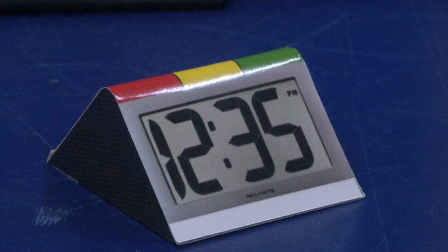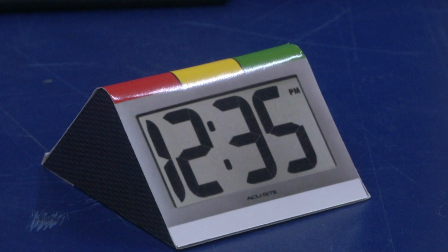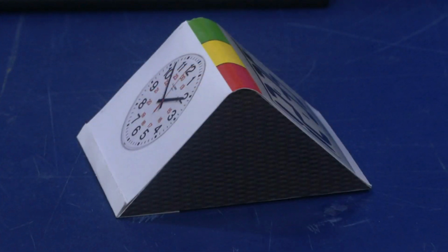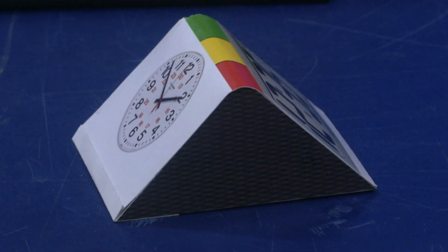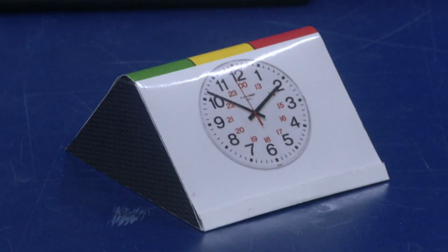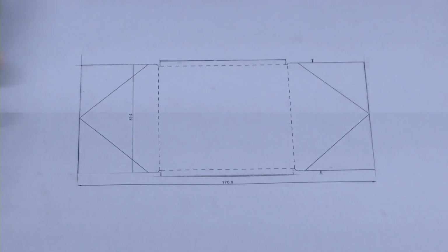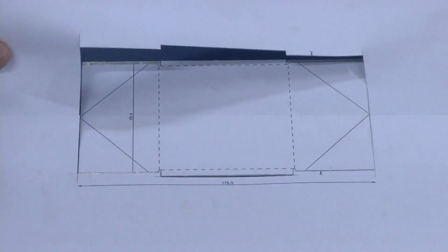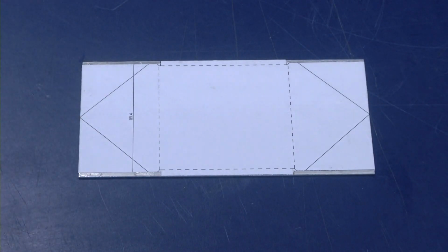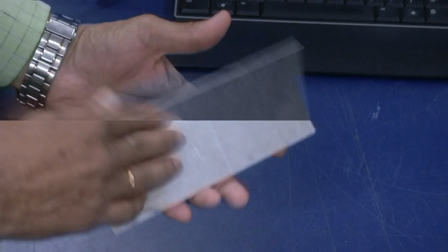My name is Singh. I would like to demonstrate the sheet metal fabrication of this timer without using height gauge or measuring tools. What I am doing here is, I will take a drawing, scale 1:1 of a development drawing, and then paste it on the sheet metal, and then you can see that this is pasted on the aluminum sheet.